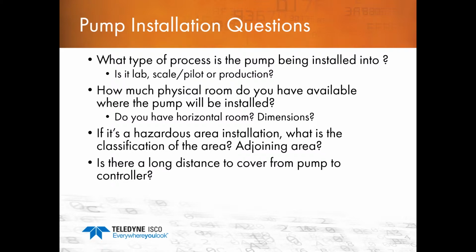Is it a hazardous area? Obviously, that's a very, very serious thing to be considering. Some pumps today have arcing and sparking mechanisms inside them, and with just a simple gear mechanism there's a risk for arcing and sparking. One little spark can be very bad. So you have to consider that when you're looking at the type of pump, the size of the pump, and where you're placing it, and optimizing its distance from where the application is actually going to be working.